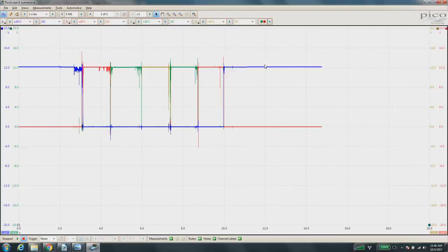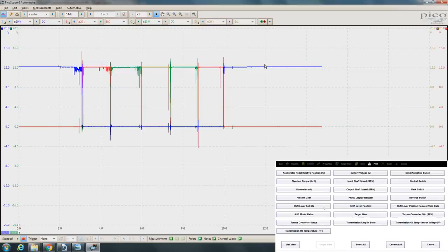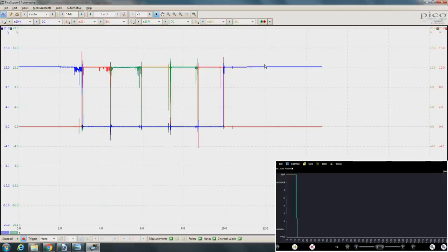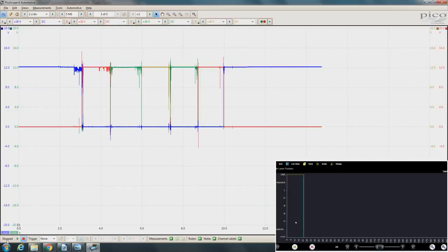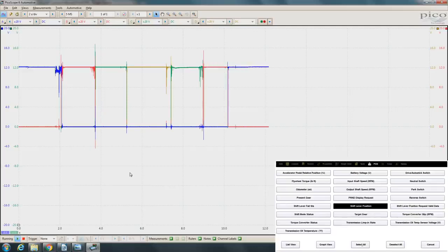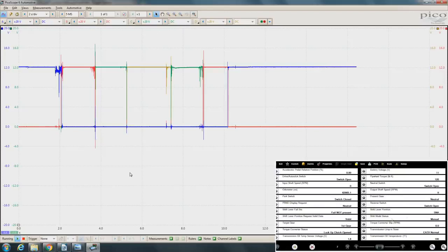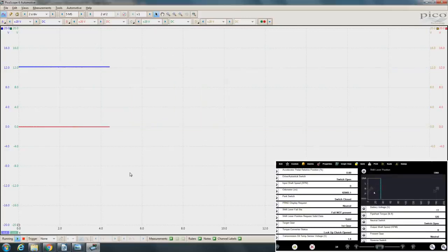Let's go one step further. Can we bring the scan tool up on the bottom of the screen? Let's grab shift lever position. Let's graph that. All right. Sorry, not that PID. Prindle display. Why is that not what I expected to see? Okay. Jim, can you do that again? All right. Maybe that's not the PID that I want. Let's look for SNA. I wonder if it's reading SNA because it's got codes in it.